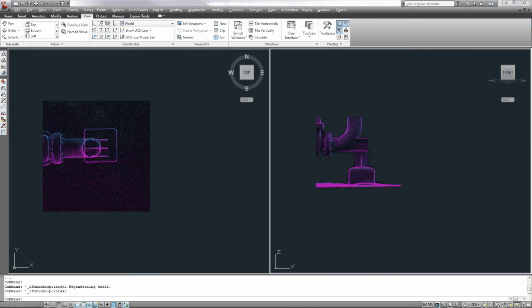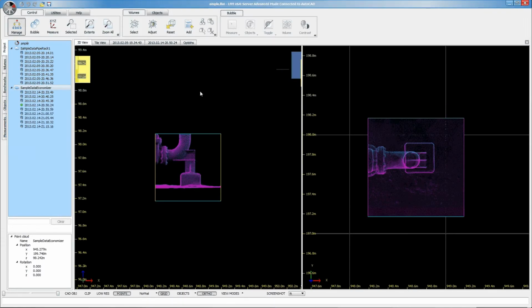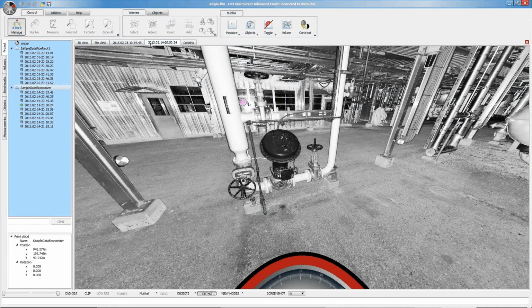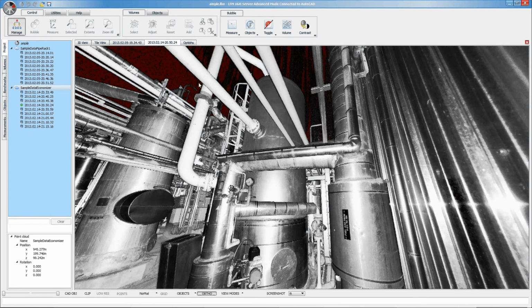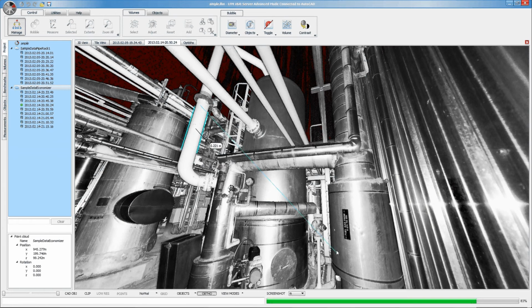The most useful thing for LFM is this, for a designer. Let's pretend we wanted to put a, actually right there, let's say we're going to tie into the mating face of that flange, and we are going to put a tie point on the center of that flange, and we're going to remove some piping. First thing we do is find out how big that piece of pipe is. So I click on diameter, and there's my piece of pipe.